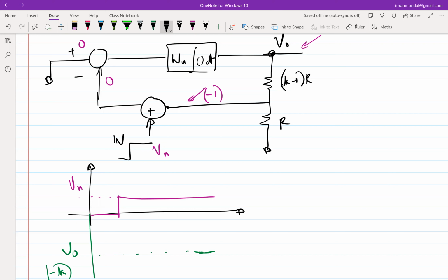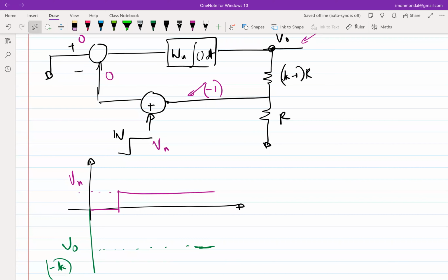So you have error in the sensing path. Whenever you have error in the sensing path, obviously your decision making will be wrong, which essentially in this case means that you have gone to a different direction. Okay, so again, output will go to minus K, and where will it start from? At t equal to t0, it will start from 0, and it will eventually settle to minus K with the same time constant.